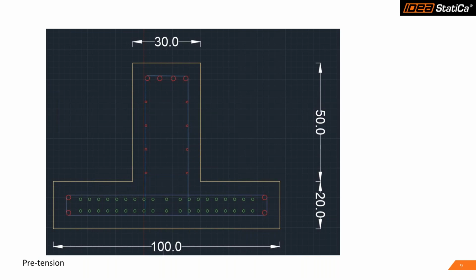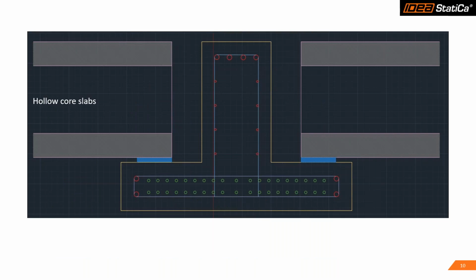Today we will conduct the static analysis of a prefabricated beam. It is a prestressed beam with pretension, and it has 38 prestressed strands, and it is an inverted T-beam, which is quite common, as far as I know, in different countries. Cheap solution, that's why we wanted.